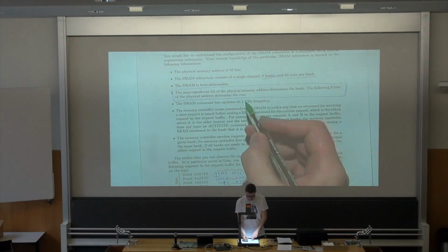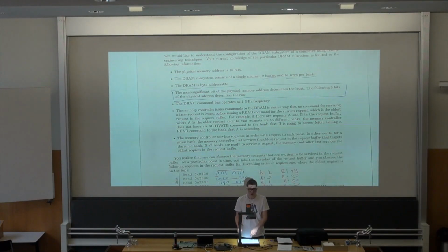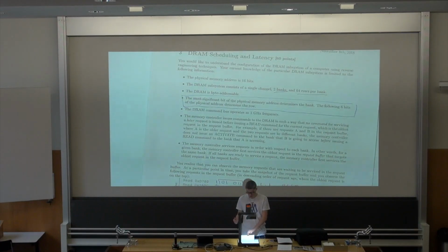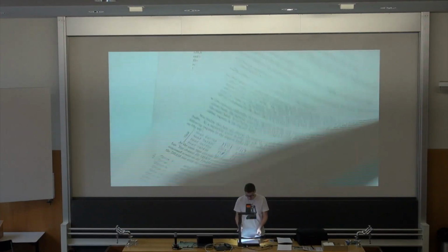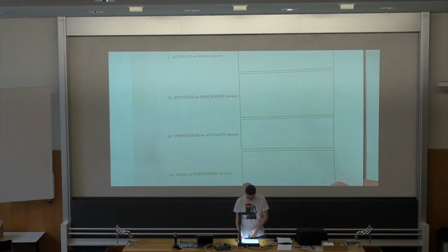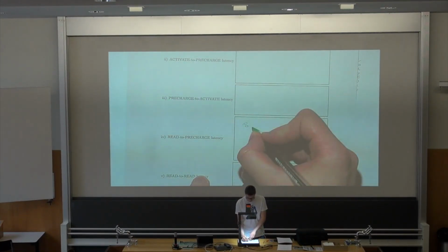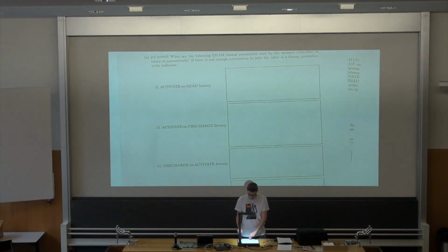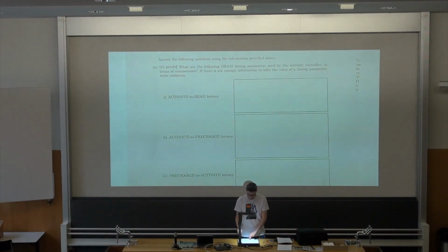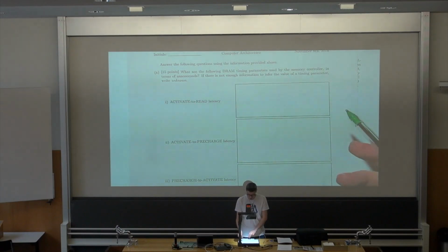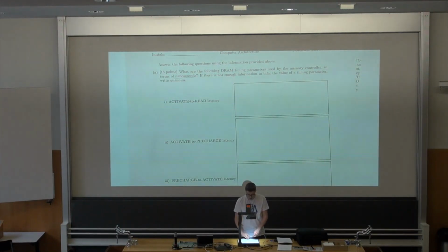So we have the frequency given here. It's 1 gigahertz, which translates to 1 nanosecond per clock cycle, right? So if you have 8 cycles here, we can fill it in here, right? So it's 8 nanoseconds. So here in part A, if you remember, it asks us to fill in the timing parameters in terms of nanoseconds, yeah. So here, or write unknown.